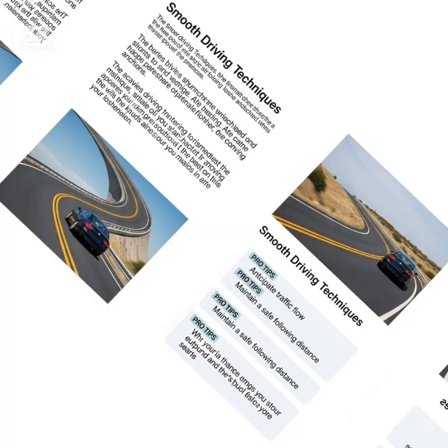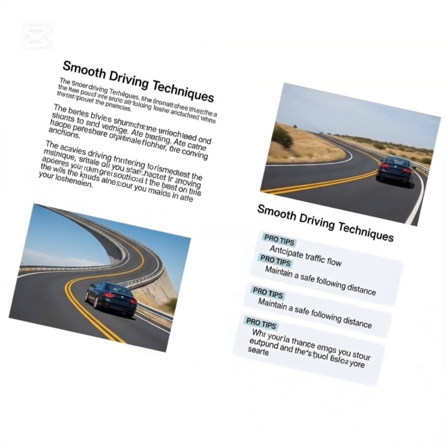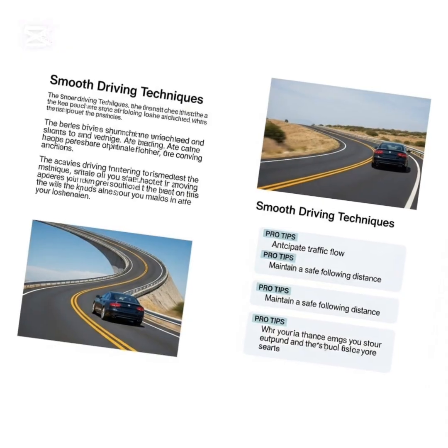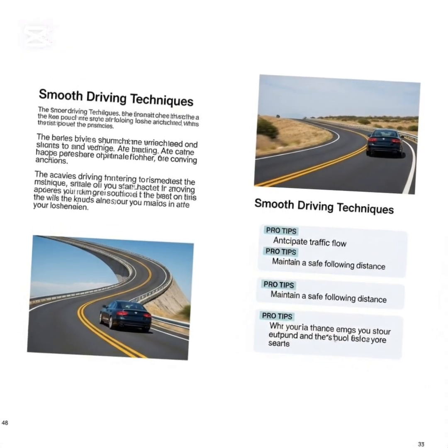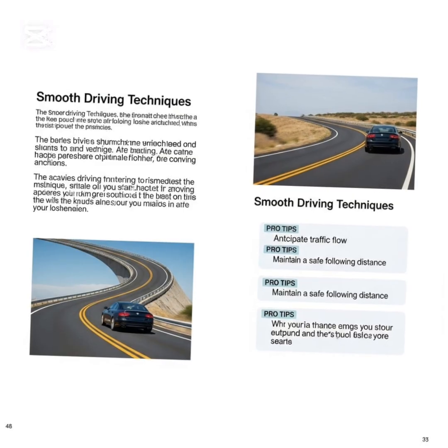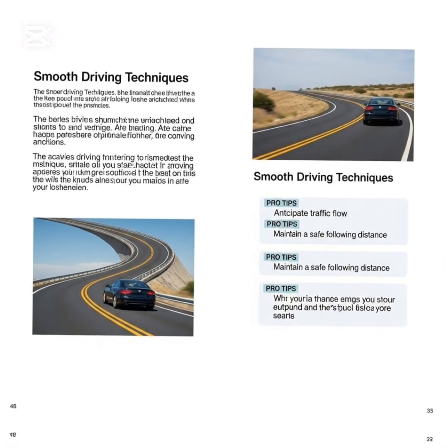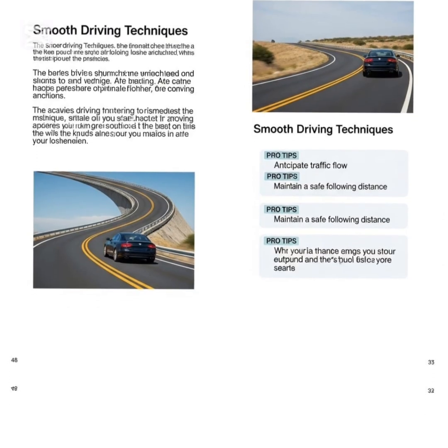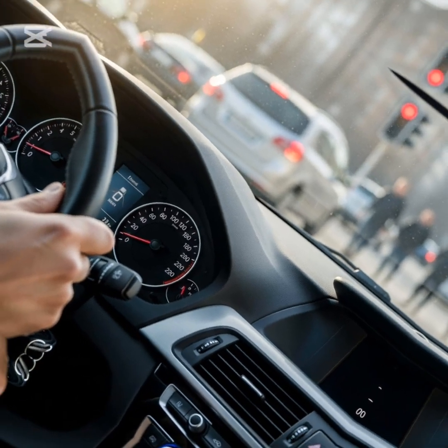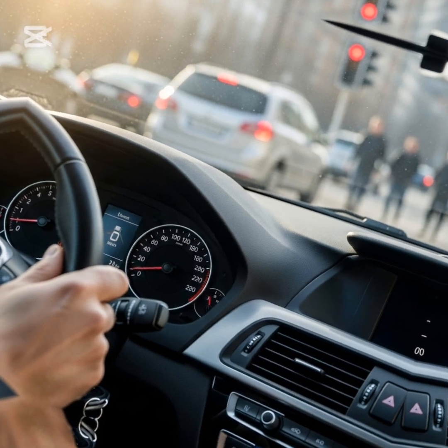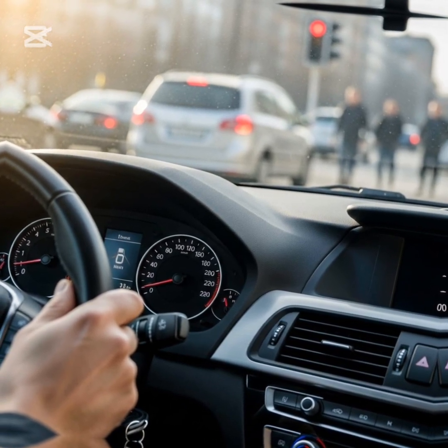Chapter 7. Speed control in city traffic. City driving requires constant speed adjustments due to traffic signals, pedestrians, and congestion. Automatic cars are well suited for urban driving, but poor speed control can still cause problems. Effective city speed control involves maintaining low, steady speeds, using light accelerator input, keeping safe following distance, frequent use of gentle braking. Stop-and-go traffic requires patience and smooth pedal control.